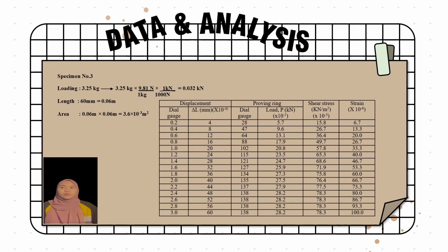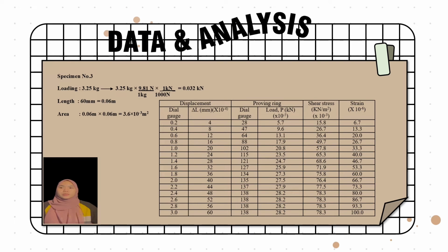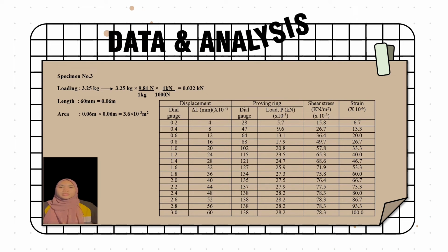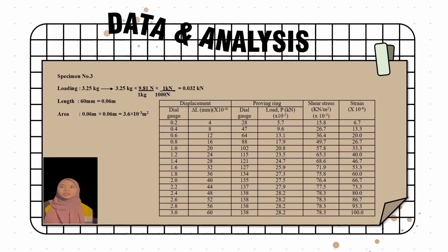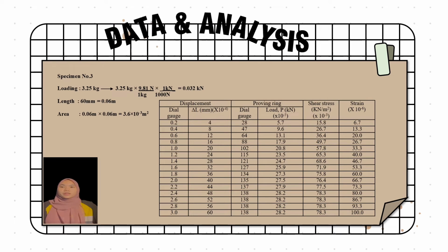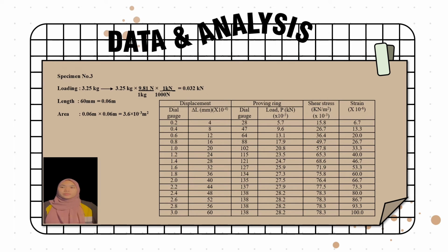There is a void ratio at which neither expansion nor contraction in volume takes place. This void ratio is called the critical void ratio. Expansion or contraction can be inferred from the movement of the vertical dial gauge during shearing.